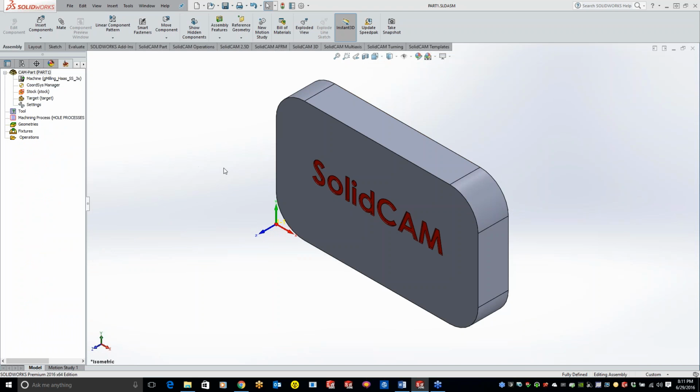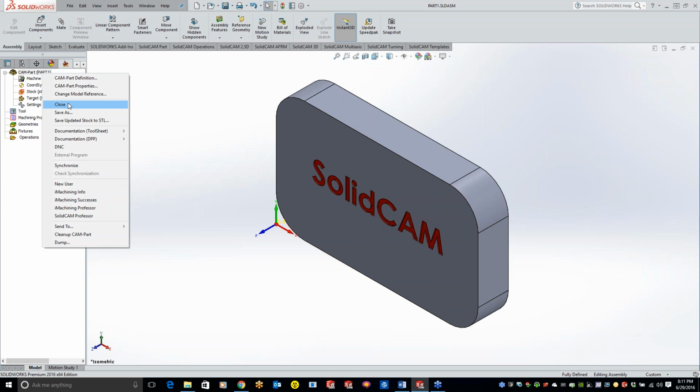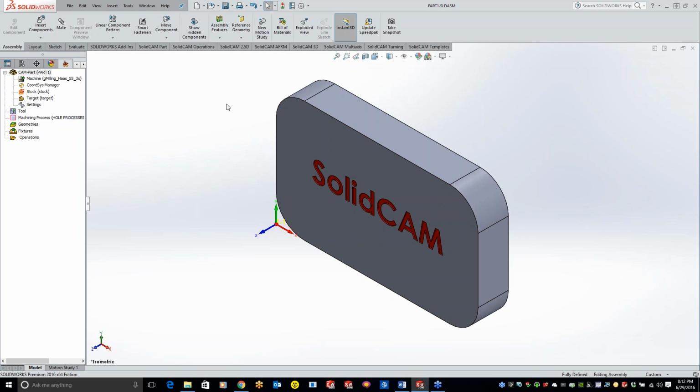Now, when I close this down, I want to kind of go over proper closing techniques. A lot of guys just want to hit the red X out. It does work 90% of the time, but the absolute best way to close out of a SolidCAM file is to just right-click on the CAM file and close. The reason we say this is because inside SolidCAM there is no save button. So everything is updating as we go.